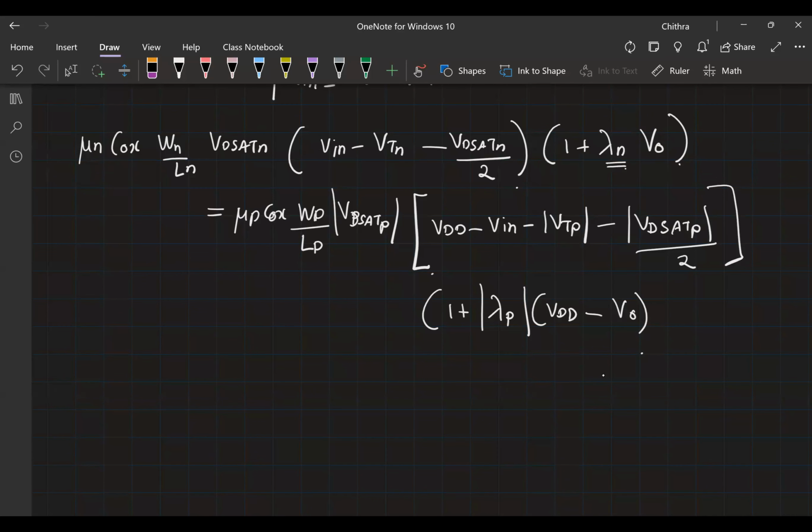So you can do the differentiation. You differentiate it with respect to Vn, find out dV0 by dVn, and then you can make the appropriate substitutions. For example, dV0 by dVn is now your G, right? V0 will be equal to Vm, Vn will also be equal to Vm. And you will get the result as follows. ID as a function of Vm.